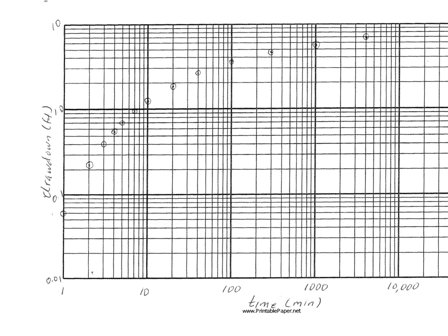For the type curve method, again, we have to have the drawdown versus time plotted on log paper, and that has to be on the same scale as the type curve. Once we have those drawn, then you slide the two papers across one another and find a match point.